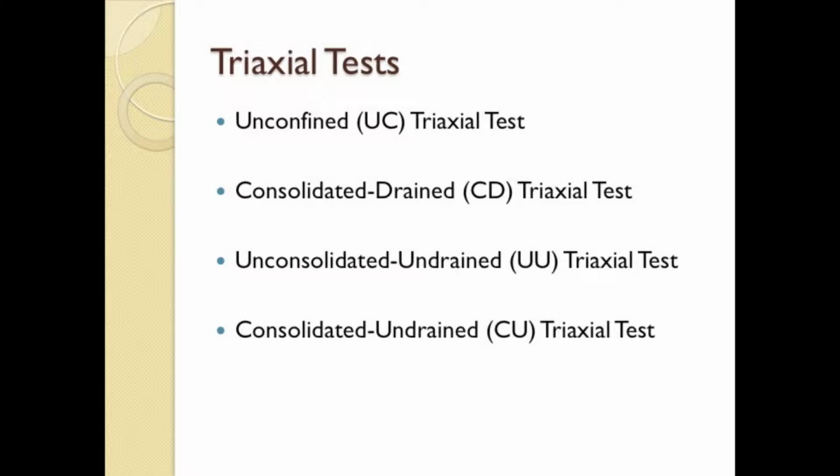Second, the consolidated drain triaxial test, which requires a confining stress on the sample and an open drain inlet. The sample is consolidated before compression, the drain line is left open in this case, and the sample is allowed to drain during compression. Theoretically, pore pressures can rise or fall during the test since water is allowed to drain freely into or out of the sample.